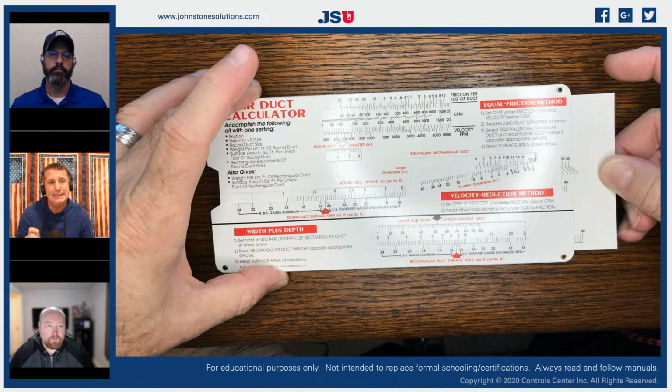We could very easily be marginal on our 1/2 inch of water column without even adding ductwork, which is why some contractors are now moving away from high efficiency furnaces on these high capacity, high efficiency air conditioning and heat pump combinations. It's because of that additional static drop on that secondary heat exchanger. We didn't design our ductwork for high static across our coils or for secondary heat exchangers.